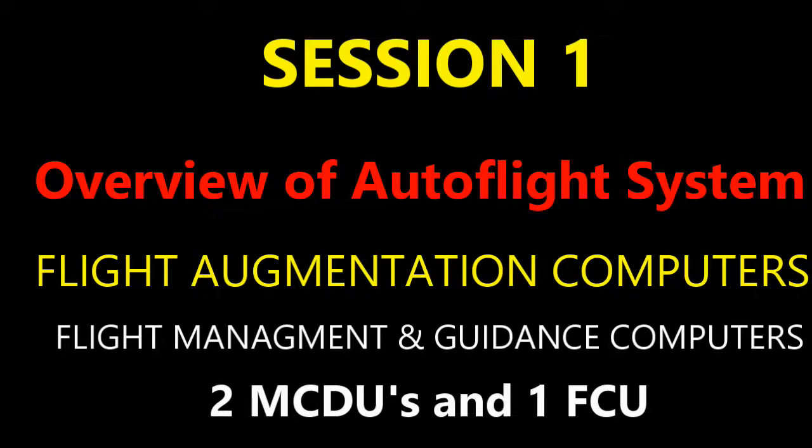All right, so here are some ideas with the controls and the indications that you have. In column 5, column 4 was approach capabilities, so that has to do with the landing. Column 5 is engagement status for your auto throttle, your autopilot, as well as your flight director. That can show up in white when it's active. Blue typically means it's armed. If it's armed, it's in blue. Otherwise, if it's engaged, it's in white.